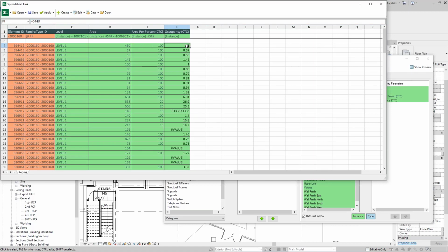You might want to get a bit more complex about this and do some things like rounding this down, round down to the nearest whole person, 0 decimal places, so I can have whole numbers of people. And if for some reason this is an occupiable space, but it's less than 1 whole person, maybe I make that a 1, or maybe I just change these maths to round up and I over-occupy my building potentially. In fact, I should do this up here so it does it for all of them, round up. And then it will rerun my maths.